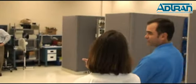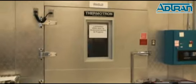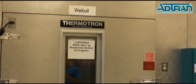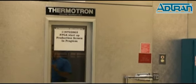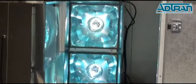So let's take a trip around the corner here. This is actually one of our large-scale chambers here that we do a lot of our cabinet testing in. So this chamber here, we've got the ability to do solar loading in it. And one of the things that always comes up with our products, and you'll see some of these here in just a minute, is what happens if we put them in the middle of the desert, getting hit by 140-degree temperatures with the sun pounding down on them. In this chamber here, we'll put thermocouples on our products in the chamber in the worst case operating environments, and then measure what the case temperatures are on our products to make sure that we don't get above any specified value. And usually at the same time, we're monitoring data flow on those to make sure nothing goes awry.